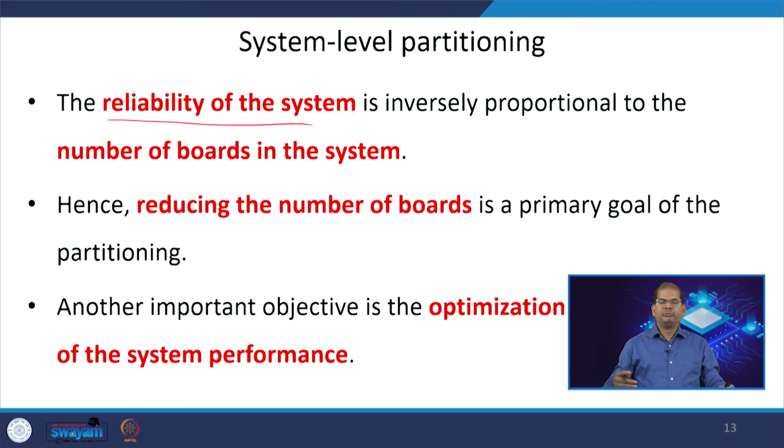If I have a higher number of boards, reliability reduces, but it depends upon how the systems are integrated or communicated with each other. Okay. So, if you have a number of PCBs, you need to put more effort in the communication between the PCBs such that the reliability of the overall system can be improved.